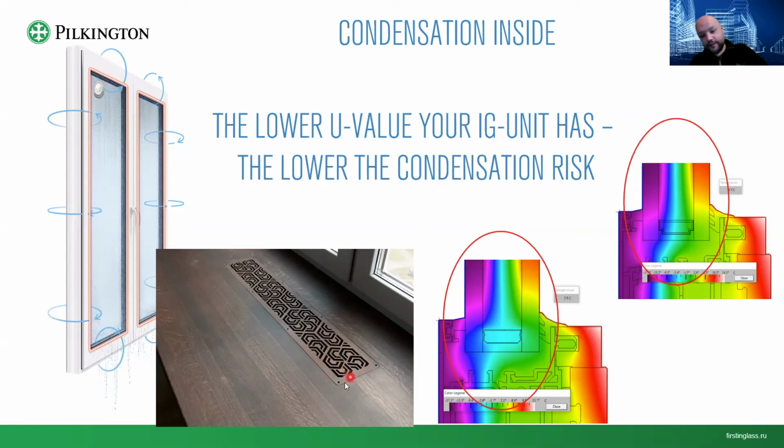So if the ventilation hasn't been made like this, then hot air will have a very long road to get to the window. And the bottom zone of the window would be much colder. So for the cold climates, this is the usual solution with which you're usually going to achieve better results and fewer claims.